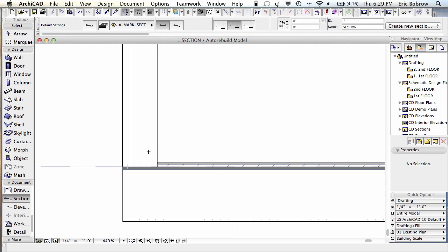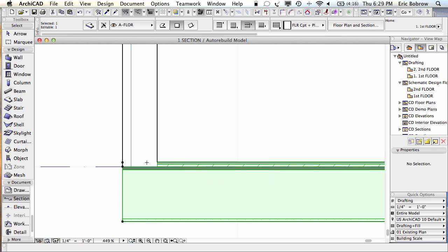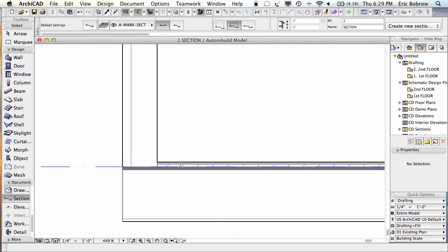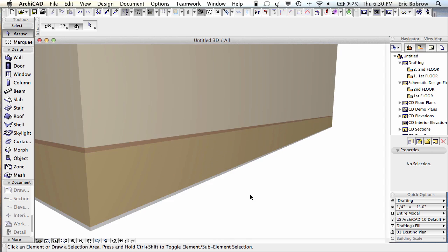And guess what? This outer wall now sticks into it. In fact, if I select the slab, you can see this little dot indicating that the slab does stick out here, but the wall had priority because these interior surfaces or skins had lower priority. Basically, they're made out of something softer or less strong compared to this. Now, if we go to 3D, we're going to see a slight change. This has now lost the carpet, and we're only seeing the framing and the underlay.